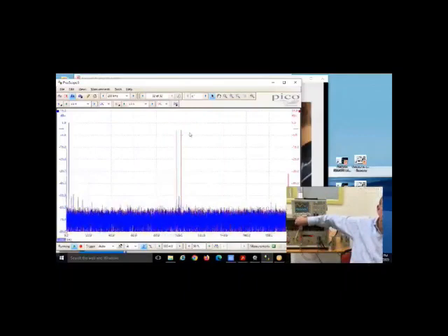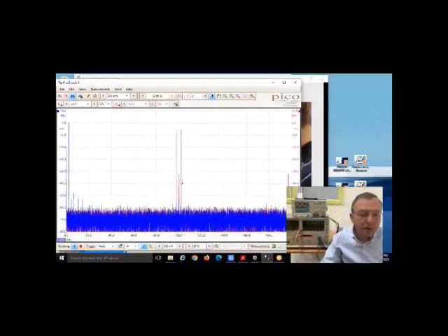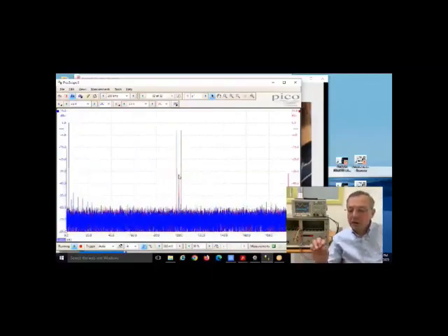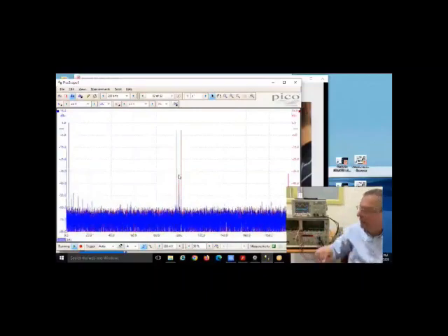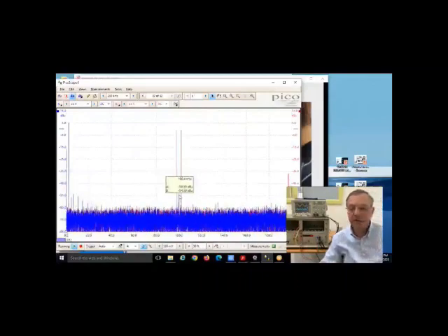So notice when I have DC coupling, there's obviously a small DC offset that's coming through. And look, you can see here, see this suppressed carrier, that's what? It's about 30, 35 dB down. That's because the small DC offsets are feeding through. If I AC couple and block the DC offsets, look what happens to that carrier. It's now 55 dB down.